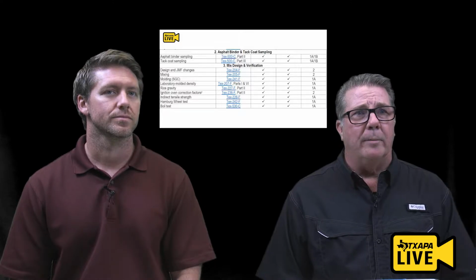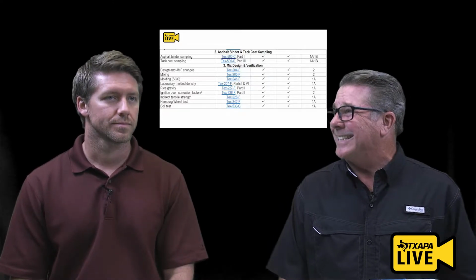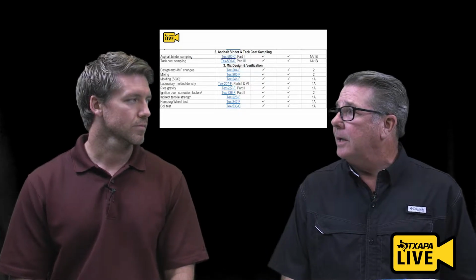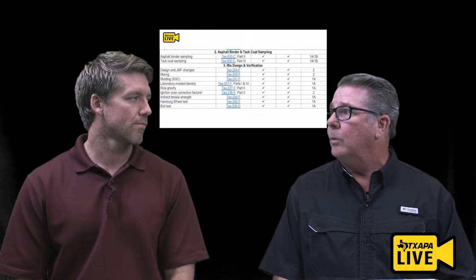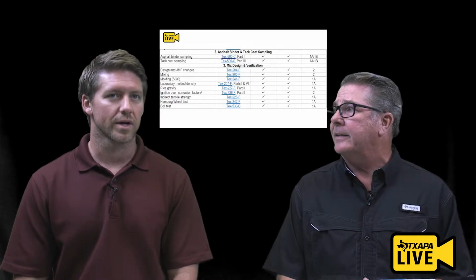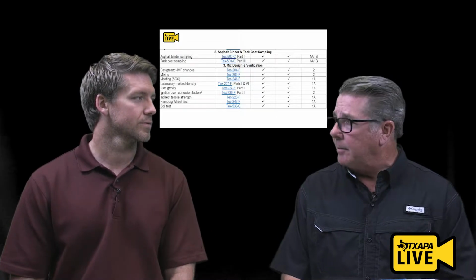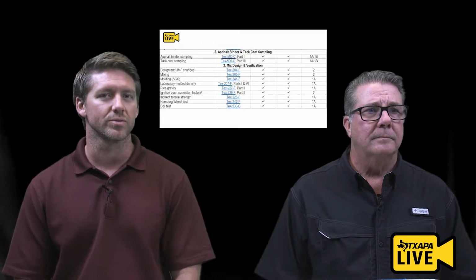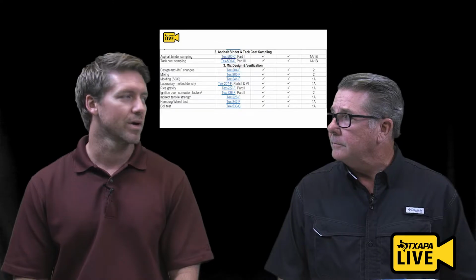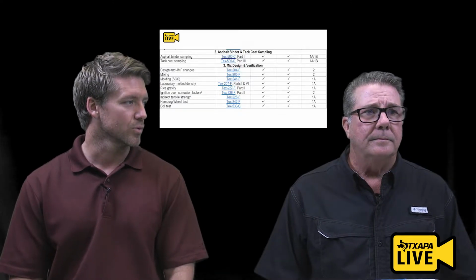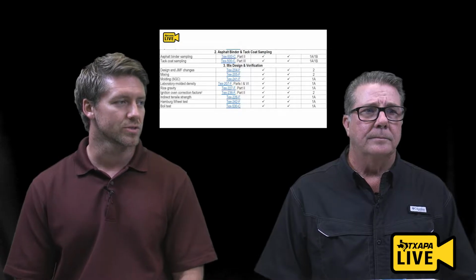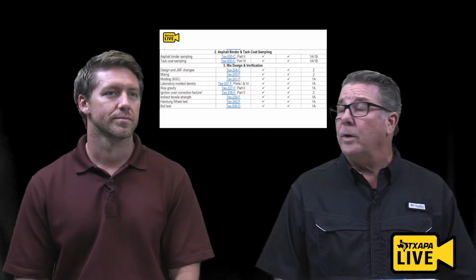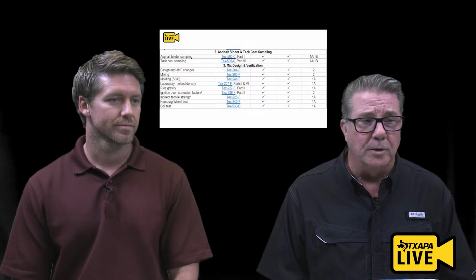Right, so underneath this requirement here, this is the asphalt binder and tack coat sampling. The contractor, 1A and 1B, will be taking a sample, and then the QA, 1A or 1B, will be witnessing that and then taking possession of that. Correct. But all the testing happens at Materials and Tests. The reason that the contractor is doing the sampling here is more so for safety reasons. It's very dangerous dealing with hot binders coming out of plants, coming out of sampling ports. So that is reserved for the contractor, and then TxDOT would be there to witness to ensure it's being done correctly. But only Materials and Tests can do the test. Correct. So there's no referee test.